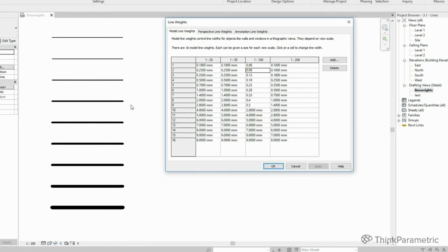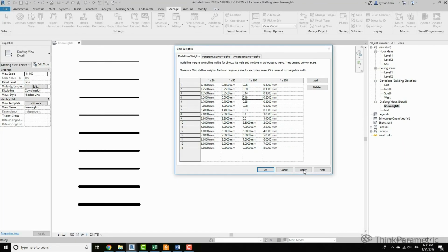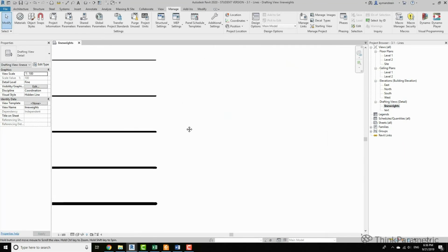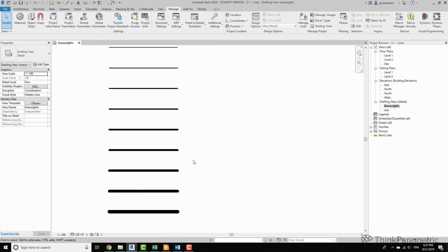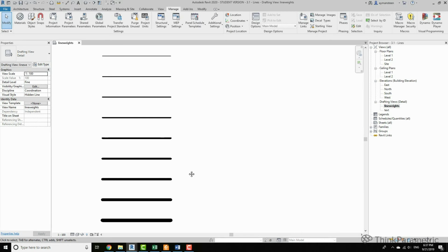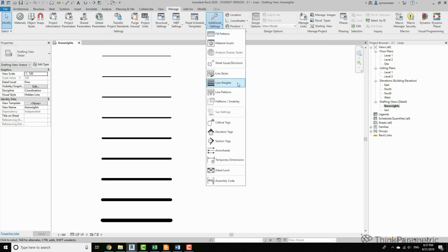You can see it's getting better. Let's try to assign slot 2 with the value 0.09 and slot 3 with 0.14. We can zoom in and check the differences closely. The settings that I'll be using will be different because it has something related to a plan visibility feature called cut line styles, which we'll be discussing in the next video. So let's apply my predefined settings and continue our lesson.